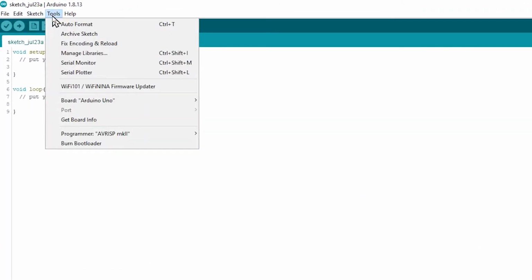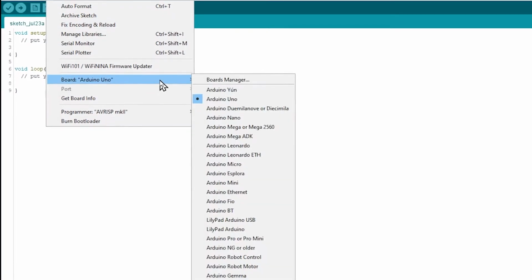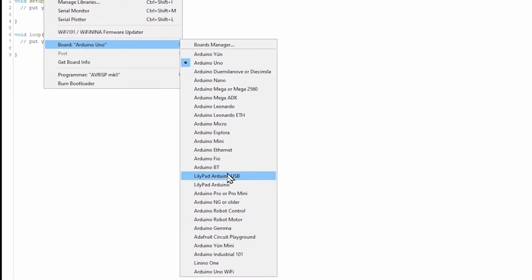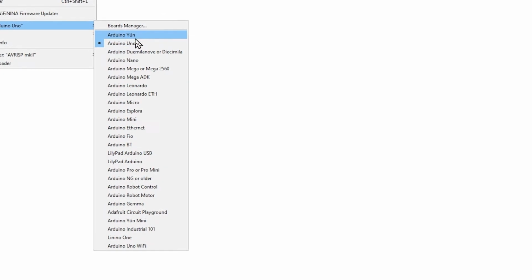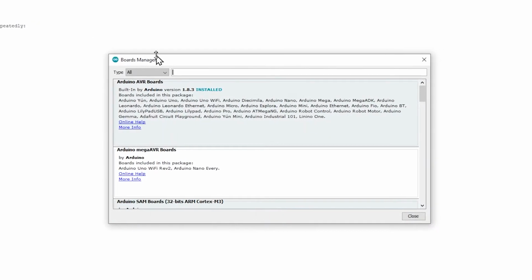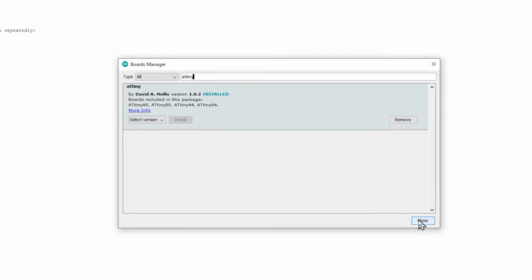After that, we go over, and this is why we have the library installed. If you go to the Arduino boards, Attiny is not listed as a candidate for the Arduino app. So because we added that link, if we go to install the Attiny, you'll see there's one application available. You install it, and now you'll have a selection of Attiny boards to install.